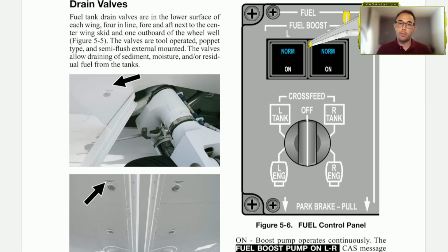But when we're in flight, we are not able to directly move fuel from one tank to another. So what we have is the crossfeed, and this is what it means when we have the don't transfer fuel. It means, just use the fuel in one tank to that engine, and separate the operation of the fuel tanks.